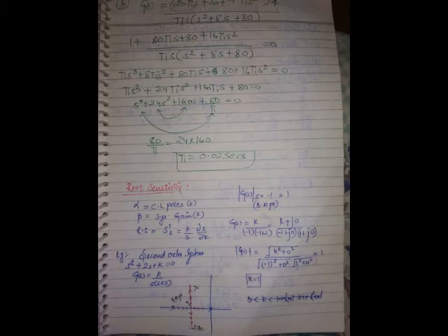AS can be considered as a derivative controller placed in the feedback path, so this is output compensation. Now what is the input of this derivative controller? C of S. So a system is said to possess derivative output compensation when the generation of its output depends on the rate of change of output. If it is in the forward path, it is rate of change of error. You understand? What is the answer? C.